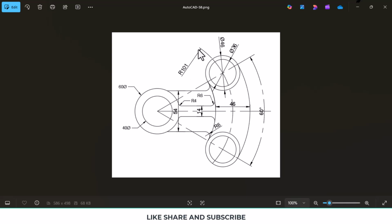Then we'll draw one circle with a radius of 101. Then with the same center point, we'll draw a circle of 36 dia and another circle of 46 dia. Then we'll copy both these circles at this intersection point over here. Then we'll draw one circle from here and tangential to this, and another circle with this center point and tangential to this. So we'll get these two arcs. We'll trim the unwanted part of the circles.